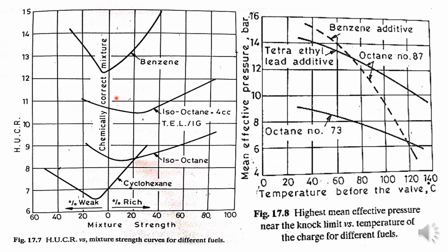The increase in pressure leads to an increase in temperature also because of supercharging, which reduces the delay period, as we already know. Consequently, the knocking tendency of the engine can increase because of the delay in the ignition period for an SI engine. If you have a delay in the ignition period, combustion will take place more rapidly. So the unburned mixture will be compressed more, hence the tendency of knocking will be very high.